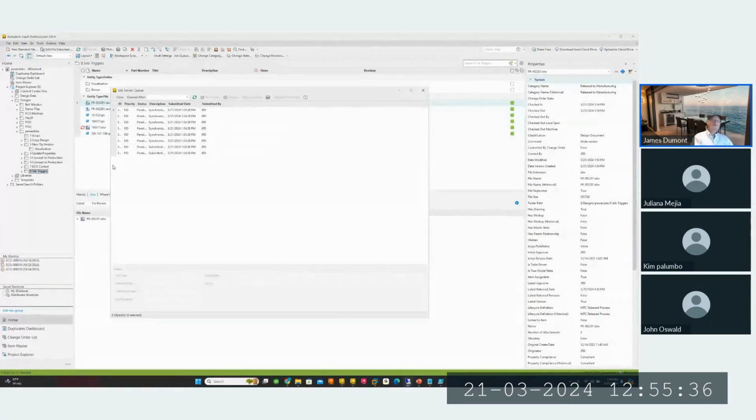So if a rule is not running, we know what's going on, we know how it works. And this is just about done processing, and then I got 3 left. So once I release it, it's going to create the DXF file, and those files also get rev controlled. As a file edits, gets updated, rev A, rev B, rev C. Same thing with the DXF files, the step files, the STL files, and if you wanted to, 3D PDF files, you could do that as well. That's something that you cannot do without Power Jobs.